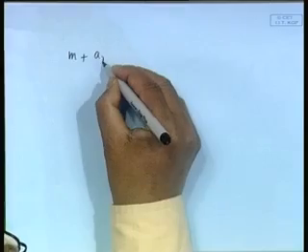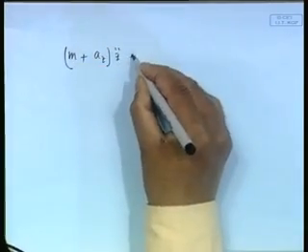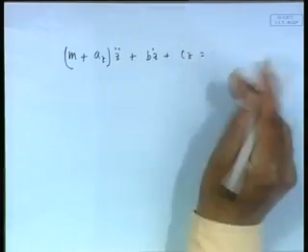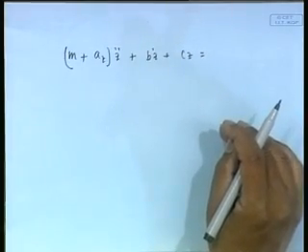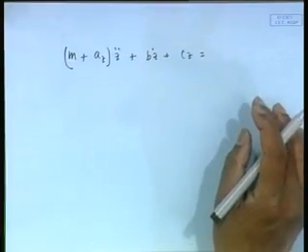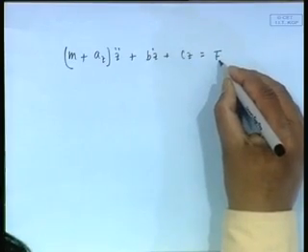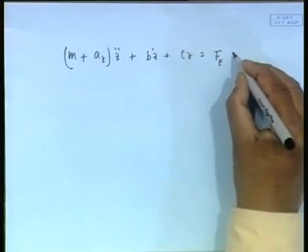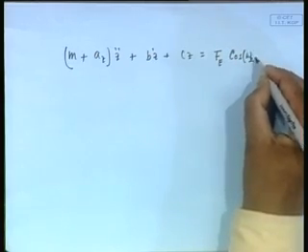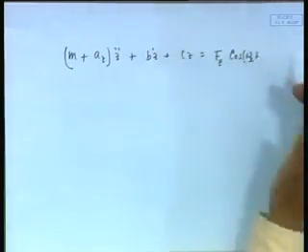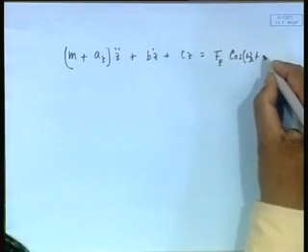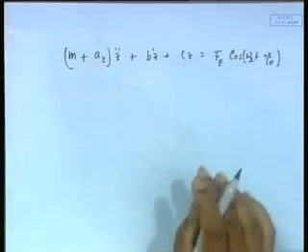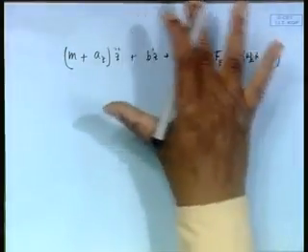So, that will look like m plus, let me call this Az, now the exciting force we wrote as F, but I explained to you that in waves everything is periodic, with a periodicity of omega e. So, this can be written as some amplitude of exciting force, and I can write it as cos omega e t. We can also put a phase here as beta, because you can also make it 0 depending on where you start from.